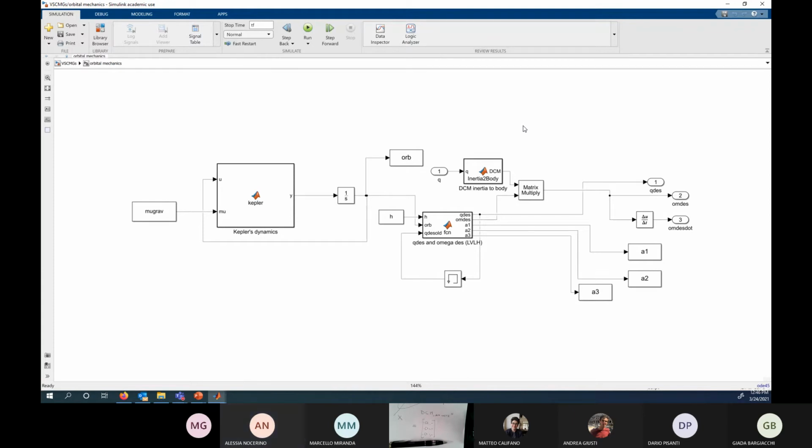Well, the equation is, we apply the transport theorem to get that form of the equation, right? Which means that the matrix of inertia is expressed in the body axis, right? Yes. And so angular velocity as well. So everything there is in the body axis. And that's because, practically speaking, as we discussed yesterday, you do have ways to measure your angular velocity with respect to ECI, of course, but it's projected in the body axis. Okay.